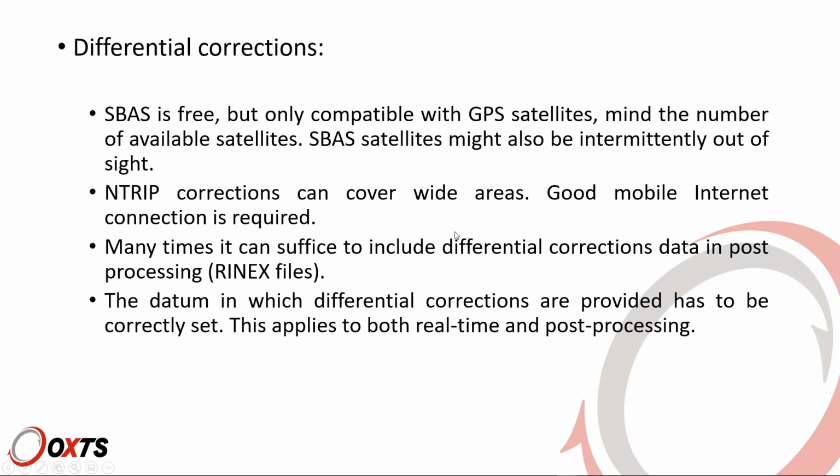You just add them in post-processing, and you do not have problems of interruptions in the stream. So that's an advantage that RINEX files will have over NTRIP. A downside can be finding a base station that provides RINEX files close enough to your test area.